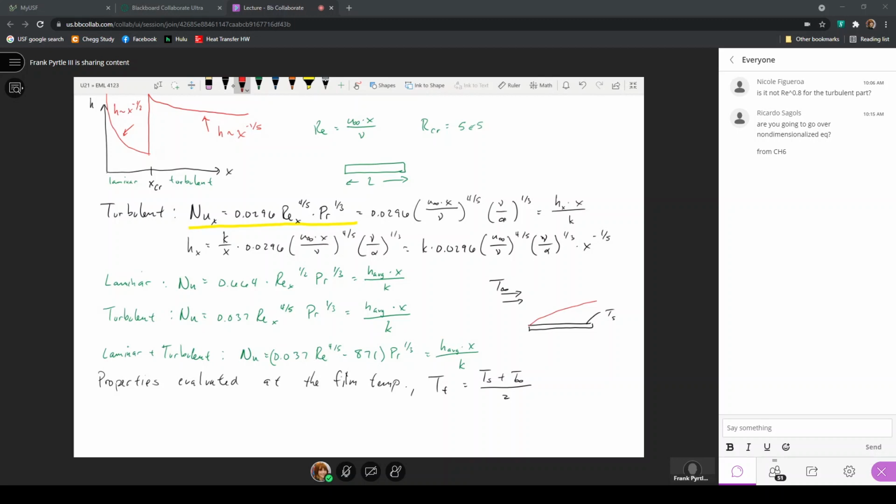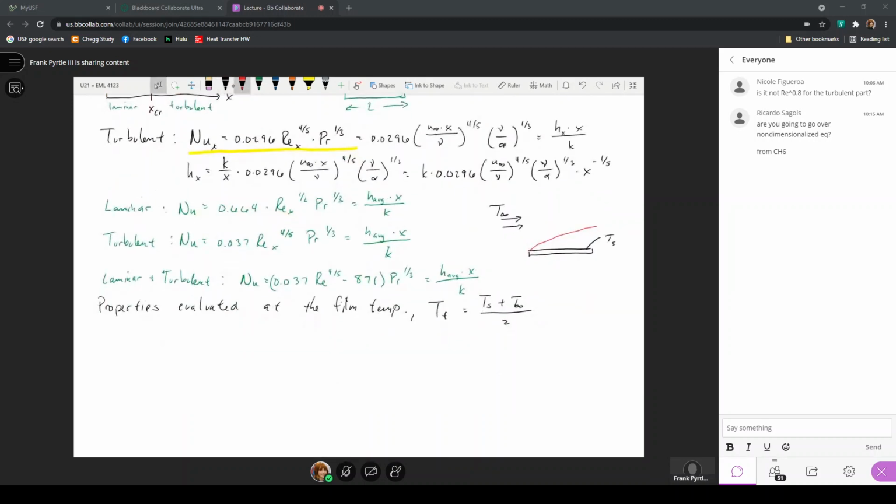It's all occurring inside the thermal boundary layer where there are different temperatures that actually exist, so that heat transfer is facilitated from the plate eventually out into the fluid. It's just that once it's out here in the fluid where the temperature is uniform, there's just no more heat transfer that's actually occurring. So we'll look at, well, how do we go about using these expressions to then calculate convection heat transfer rates? So here's an example here.